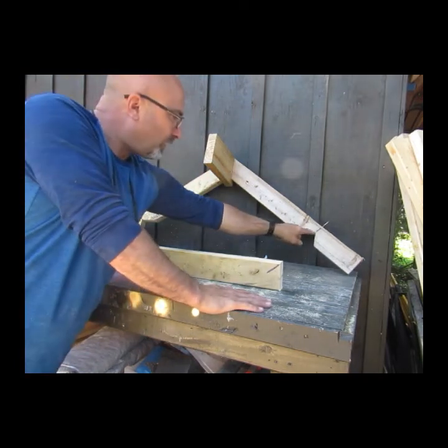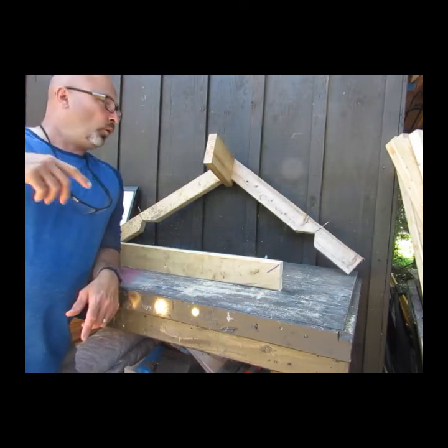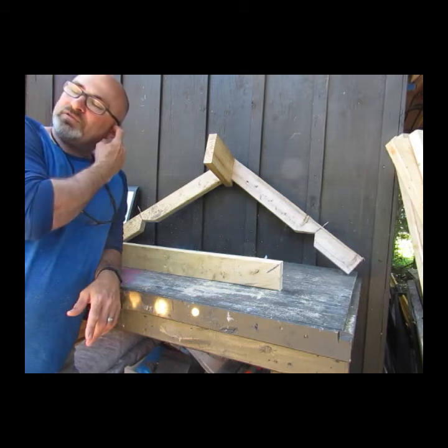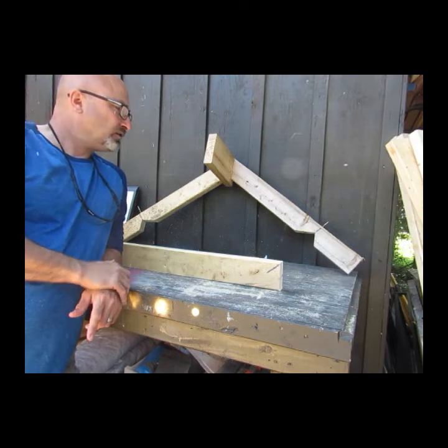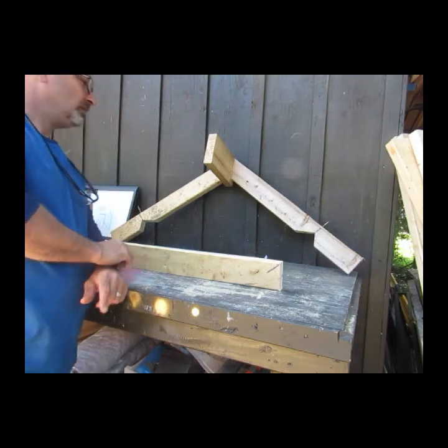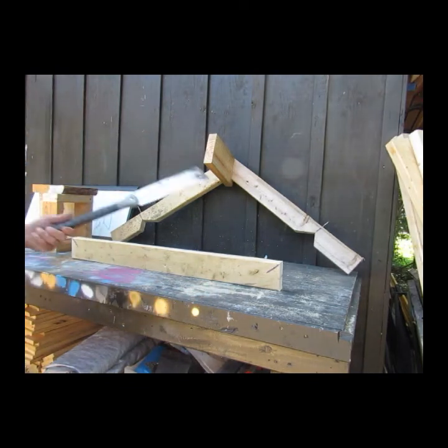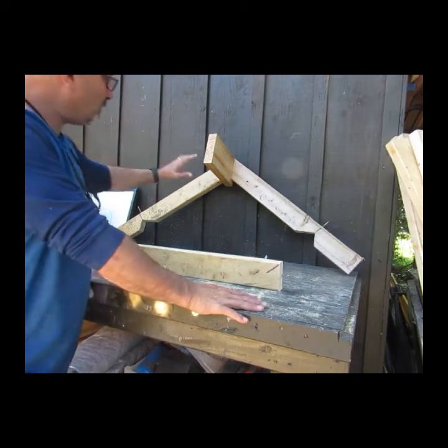So this notch right here has to be calculated paying attention to the rise and the run, or the slope, of your roof. We had a 7/12, so that worked out to, I thought it was 30, but it was closer to 35 degrees by the time I set my saw up. I cut that with a little skill saw, and then finished it off with my lovely favorite little hand saw, my Dozuki saw. Anyway, so what we've got now are the rafters.